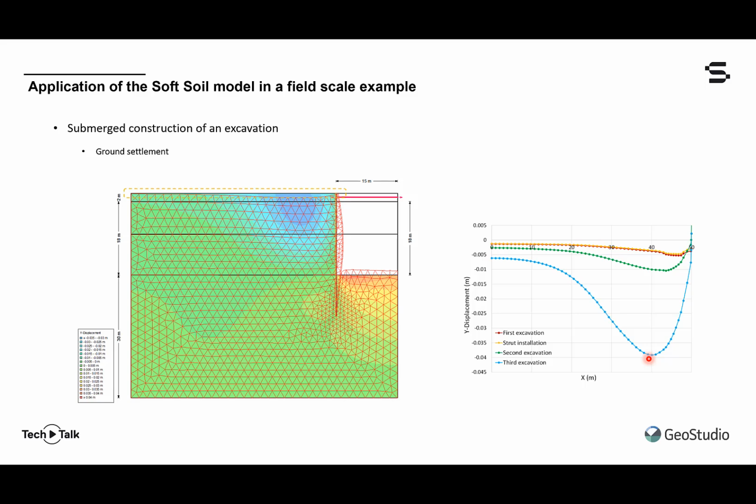The overall displacement pattern is downward towards the excavation, causing the ground surface, you can see, to heave. There's a little bit of heave. This is the suspicious part near the portion of ground right up close to the wall, and that is primarily because the top of the wall rotates counterclockwise back into the soil profile, causing a little bit of heave. So that aside, you can see here that the maximum amount of settlement is around 4 centimeters at about, well, right in the middle of this contour.